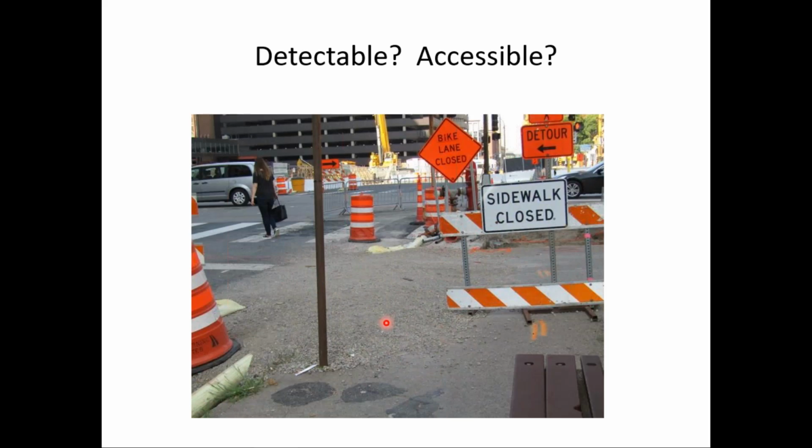So really what they should have done here, again, this is neither detectable nor accessible. They probably should have closed this sidewalk at the beginning of the block to just keep pedestrians out of this area and maybe detour them to the other side of the street. Although in this case, I'm not sure there's an accessible route on the other side of the street either.